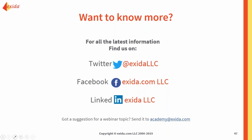Okay, the next question is talking about if they're using generic sensors. How would this be certified to use? So I am assuming that you're talking about generic failure rates for the system or a non-certified device. If you are talking about a non-certified device, you can use generic failure rates to calculate your probability of failure on demand and all of that information. You can use those generic failure rates to do those calculations to see where you stand.